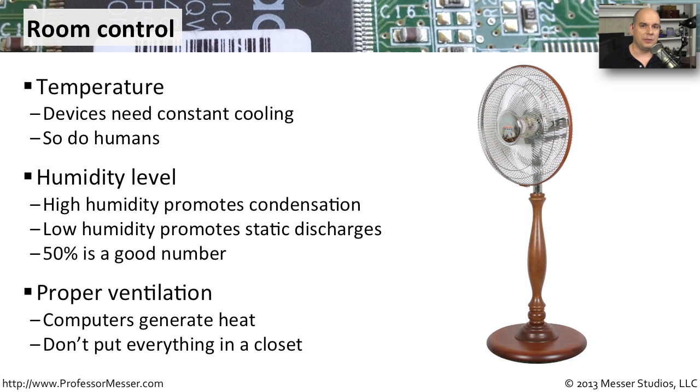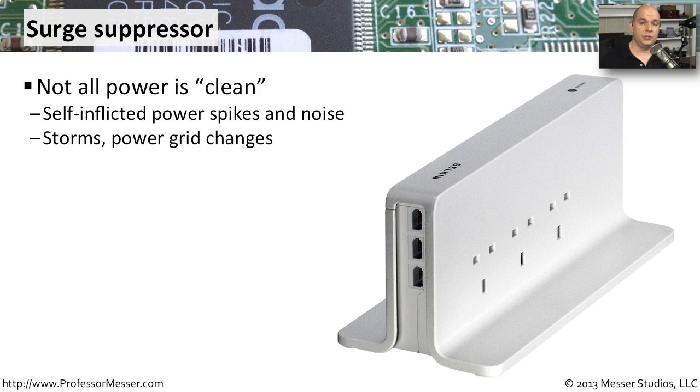Obviously, that's not the optimal environment for batteries inside of a UPS or your computing components or your networking equipment. Check your manufacturer's documentation for the temperature ranges that are appropriate for those devices and make sure those areas are well ventilated. The power going into our computing systems is incredibly important, and we want to be sure that we have the cleanest power going into our PCs.